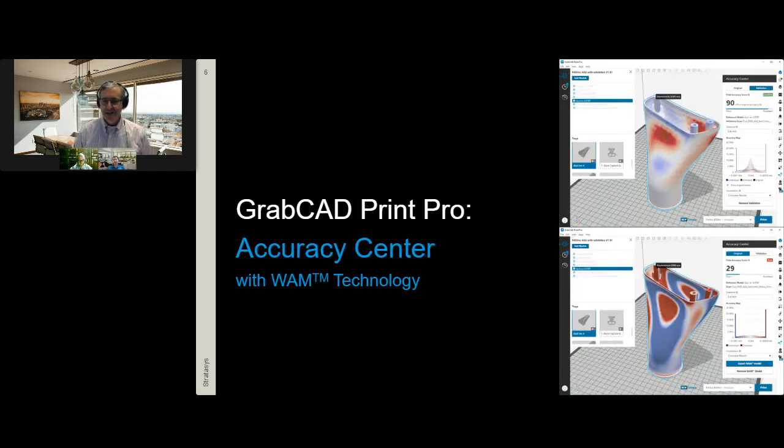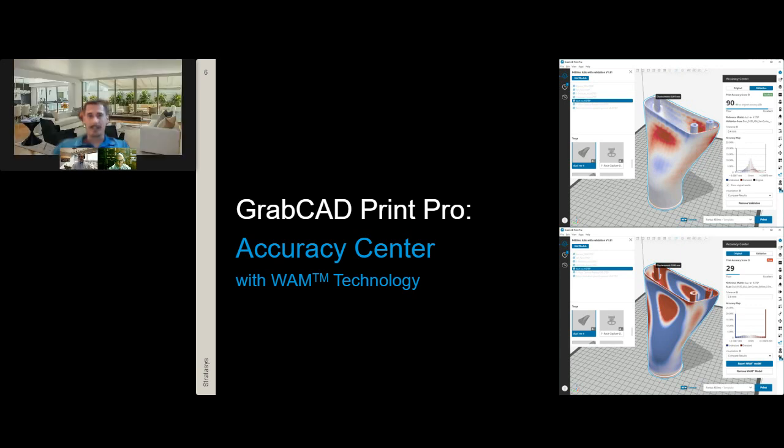Sure. Yeah. So like Victor was saying here, this is integrated into GrabCAD Print Pro. This is a Stratasys product. So the first module we're going to talk about here is what we call the Accuracy Center. And so what this module does is it takes a scan of your printed part and it compares it to the CAD model and then scores the accuracy. So you can see on the images to the right, it provides a nice color map, score, and a histogram to show the accuracy of your printed part as compared to the CAD model.